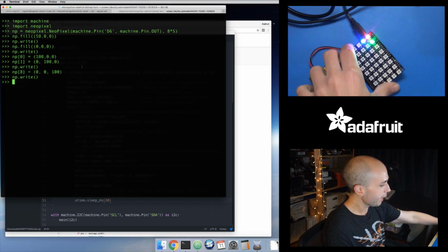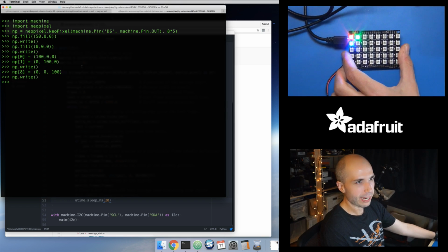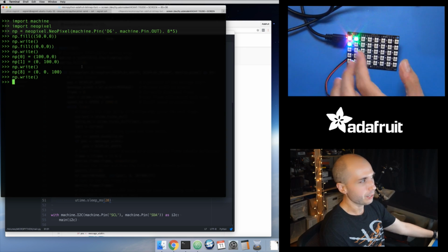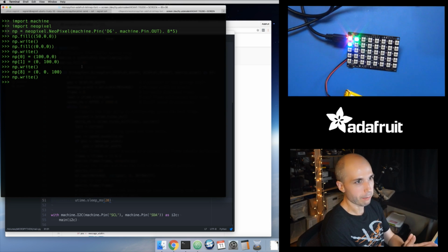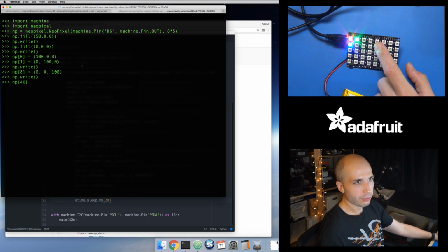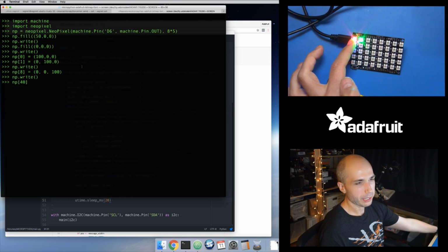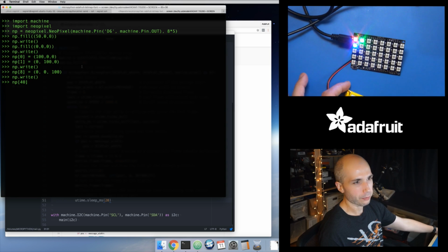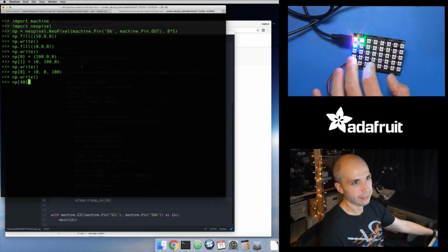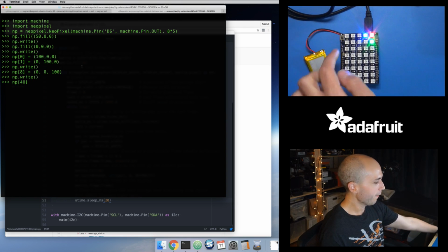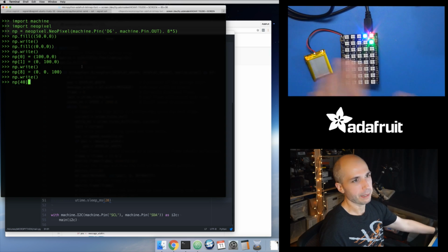So if I wanted to draw a character, it would be in this orientation because it's going to start at 0, 0. And I'll show you how you can convert that, because this array of pixels is just one-dimensional. It goes from 0 to 40. It doesn't have a concept of an x and a y, but I'll show you how you can do that. But if I just tried it like this as is, I'm going to be drawing in a weird way because I'm only going to have 5 pixels, but my font is 8 pixels tall. And I get more pixels across, but it's going to be cut off. So I really want to transform this so that I can draw with my origin in the left up here.